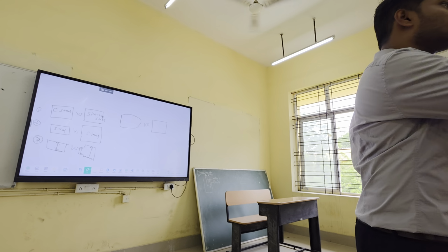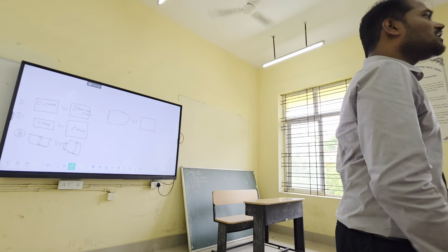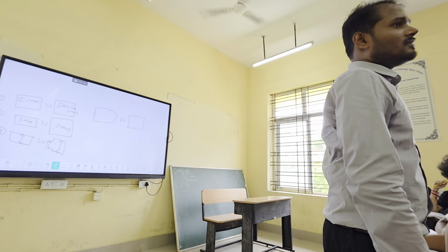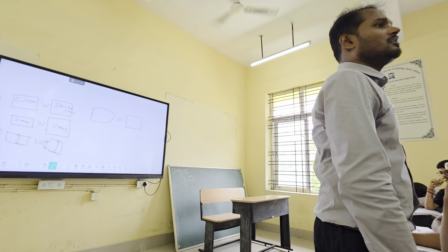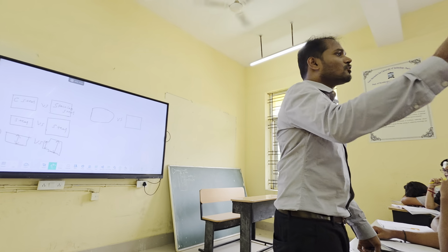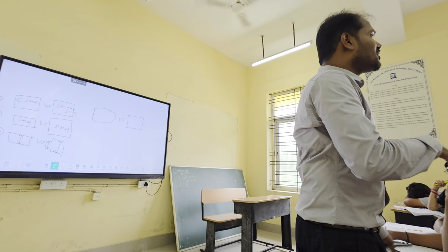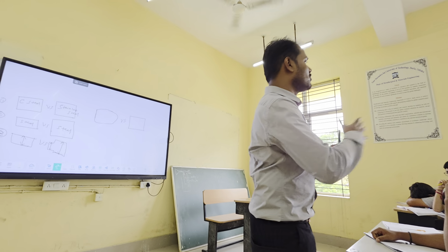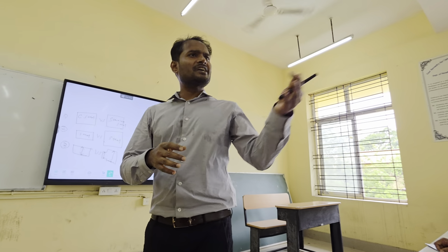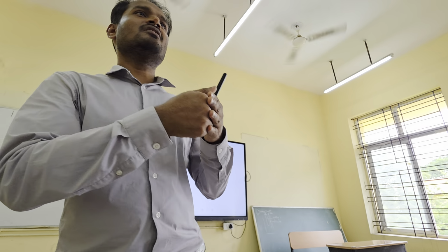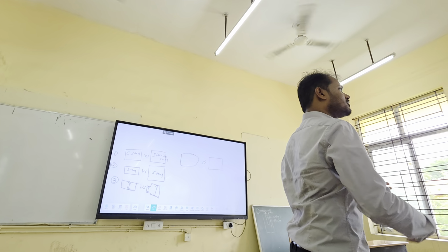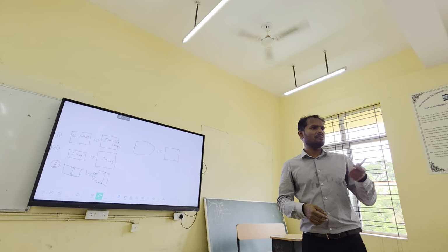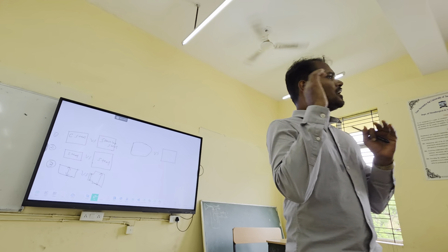Carbon atoms always go into the interstitial sites, right? It also generates lattice strain around it where it goes. So strength will increase automatically because the dislocation has a strain field and your lattice also has a strain field. They will interact and the dislocation will stop. It cannot easily move. You have studied interaction, dislocation interacting with atoms or molecules or these things. Already you studied it in maybe DBM, I guess. Yeah. Okay, anyway, you understood my point.